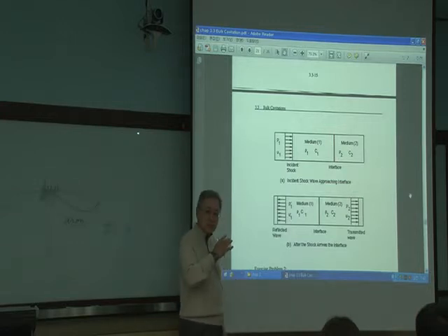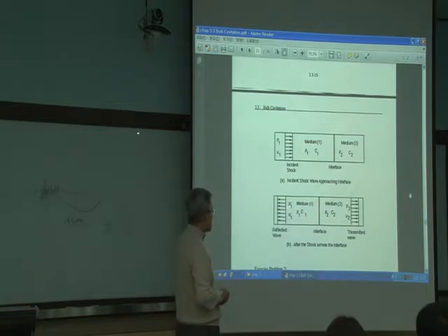Some will penetrate, transmit into fluid medium 2, and right at the interface, some portion of the shock wave will reflect. So right here, reflection, I use a prime: P1 prime, U1 prime. And rho 1 C1 is the impedance for fluid medium 1. This is fluid medium 2, and this P2 and U2 is transmitted.